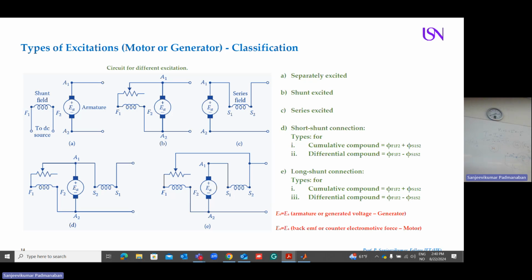This is my rotating part, which is an armature, in parallel with my field winding electromagnets. This is called a shunt motor. What is a series motor? The rotating part is in series with the electromagnet, which is the field winding, in a series motor.